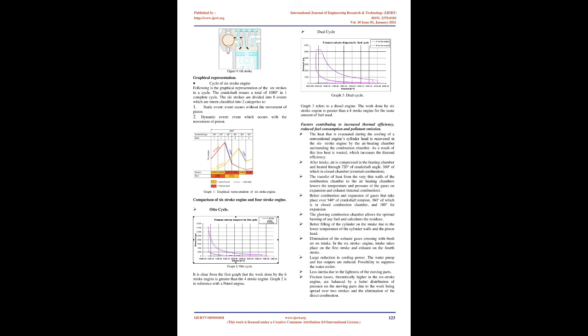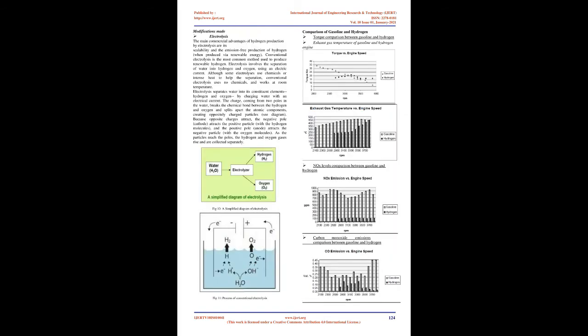3. Bajulaz 6-stroke engine. The Bajulaz 6-stroke engine is similar to a regular combustion engine in design. However, there are some modifications to the cylinder head, with 2 supplementary fixed capacity chambers, a combustion chamber and an air preheating chamber above each cylinder. Figure 2, Bajulaz 6-stroke engine.